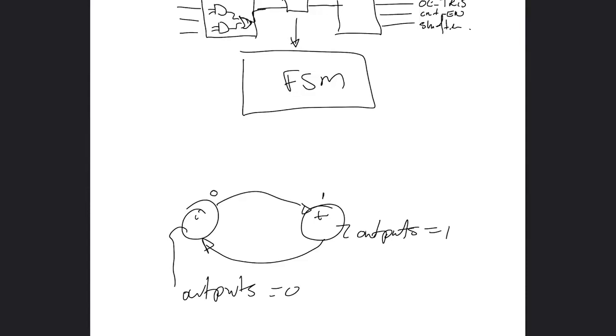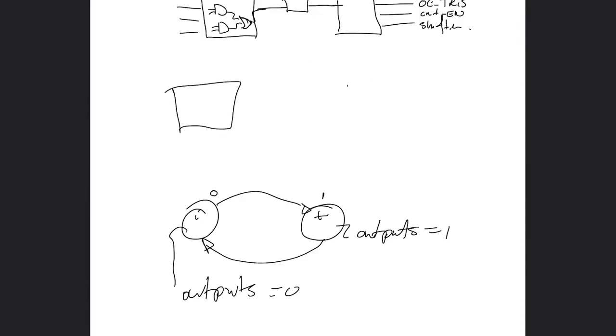Right, so what I was about to say when I interrupted myself is you need to think about the fact that you have 3 independent components. You've got the state machine that I've drawn there. Then you have a counter, and then you have a shift register. And you have to control those independently using your state machine.